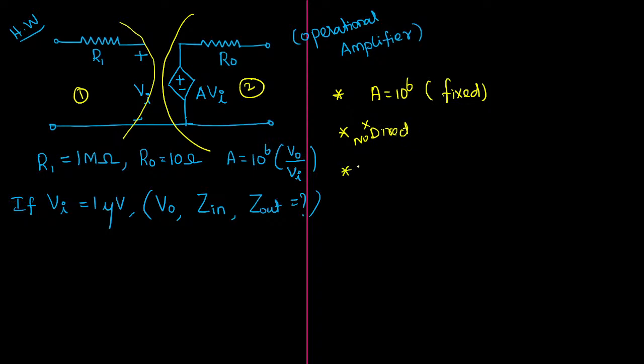And the third thing is, the secondary part of the voltage can be controlled. This is called V0 basically because this port is always open. So the value of V0 can be simply written as A times VA. In an operational amplifier, the output voltage formula can be written as V0 equal to A times the input voltage VI. That is the next conclusion. The value of A will be known to you. Practically it is 10 power 6. Ideally it is very, very large.